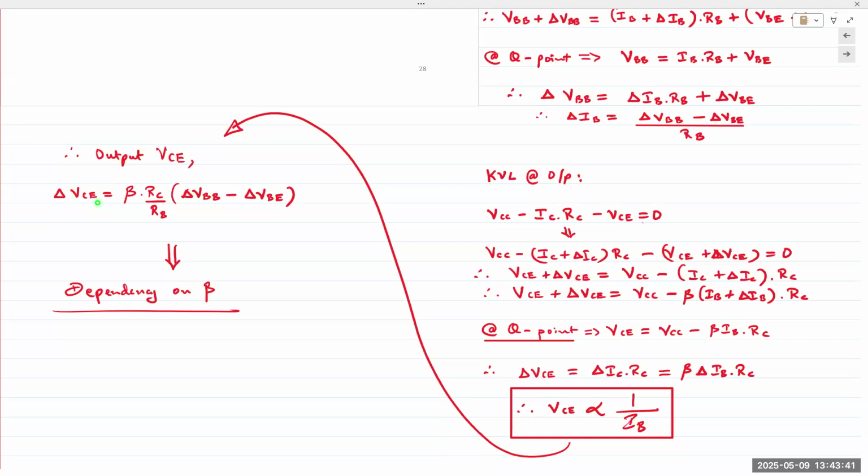And we actually saw that in the lab when we reduced the input signal going to the amplifier by a factor of 10. Remember, we used a voltage divider network. We sent the input signal in there, and the output signal was very large, especially when we used a bypass capacitor. And if it gets too large, then it's going to drive the transistor into saturation or cutoff, which would mean distortion in our speakers.